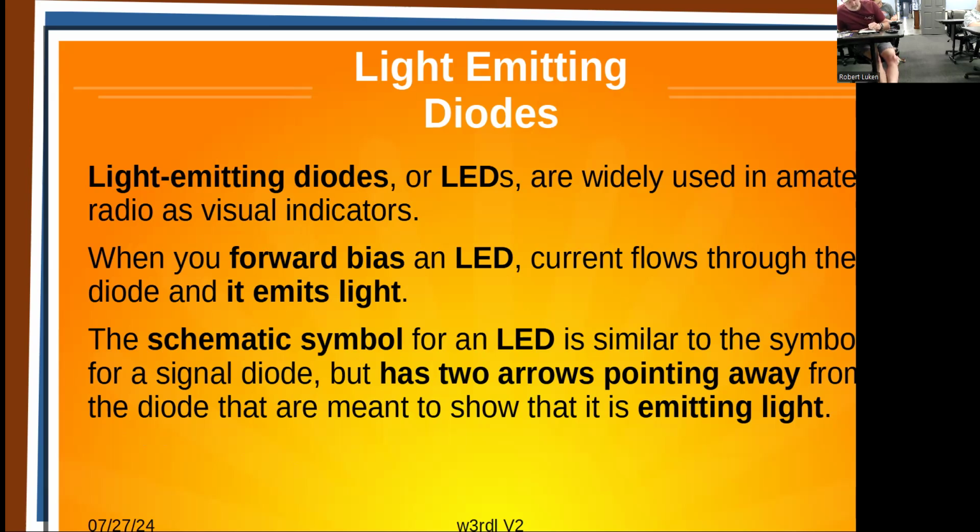But when you forward bias an LED, just like a normal diode, you can have current that flows. Because it's made from different material, the band gap is different and the threshold bias voltage is different. It's usually up in the volt range, 2 or 3, 3.5 volts, depending on the diode. And it's somewhat affected by the color that they want to produce.